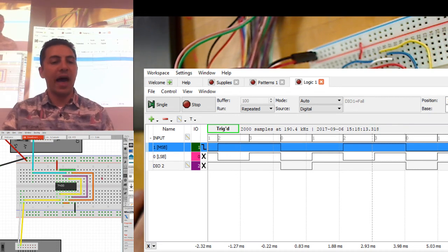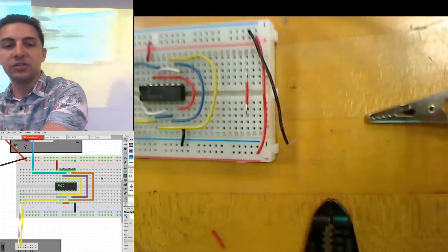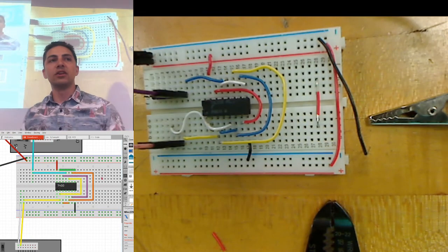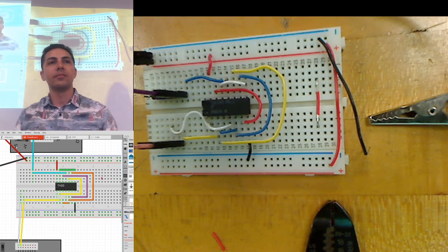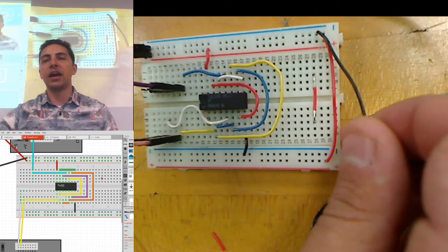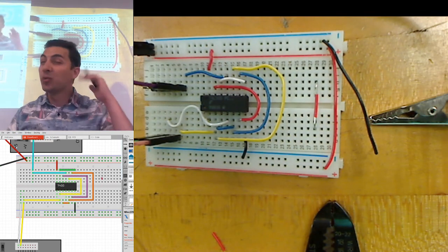The reason for that is the most common problem with all ECE260 wirings. What's the problem with that? Do you see anything that looks out of place? What's wrong? Yeah, not having a ground connection is a great way to get really weird results. Like really weird.